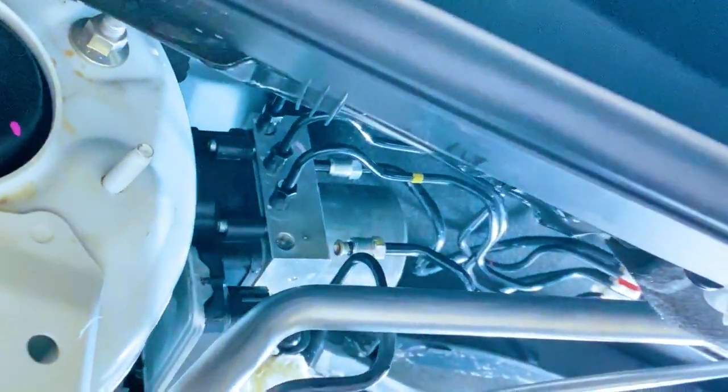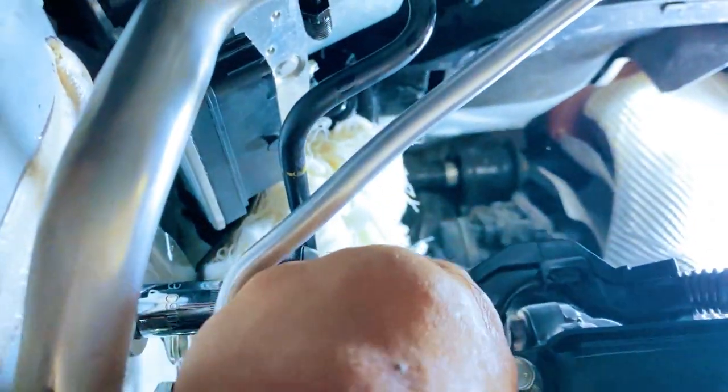Check the 12-volt battery. Before doing any major diagnosis, Toyota gives us a very important instruction. Check the auxiliary battery voltage. For a 12-volt system, the specified range shown in the repair procedure is approximately 11 to 14 volts. If the battery voltage is below 11 volts, Toyota instructs us to recharge or replace the battery before continuing with the diagnosis. This step may look simple,